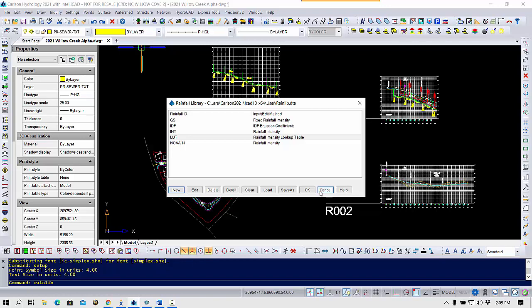It requires rainfall accumulation of 6 hours and 24-hour storm durations for the 2 and 100-year storm, and the elevation of the location. The rainfall depth can be entered either manually or from the TP40 maps. The computation button computes the rainfall intensities and the IDF coefficients.